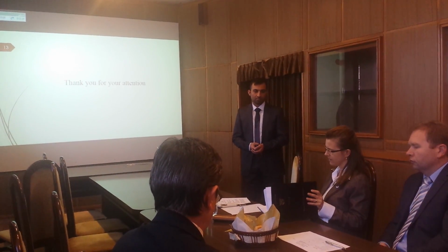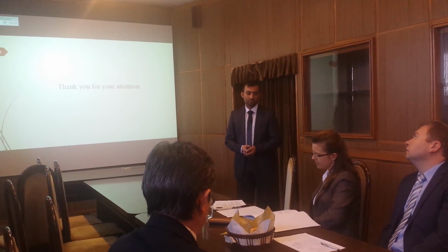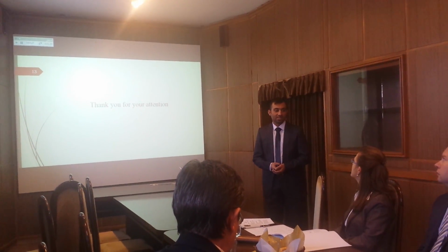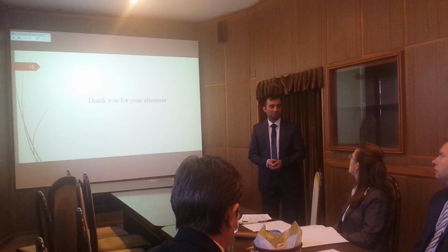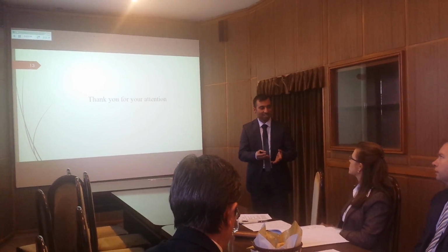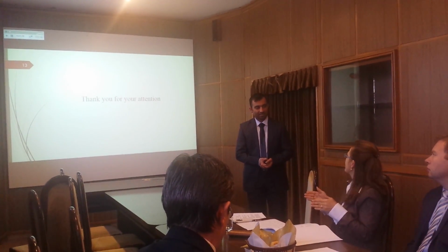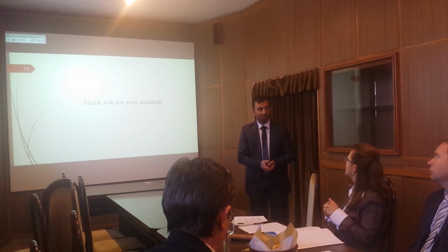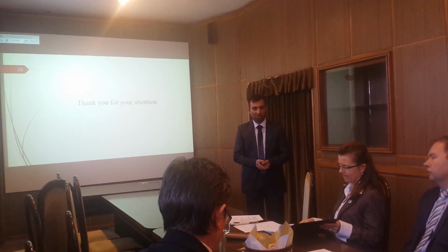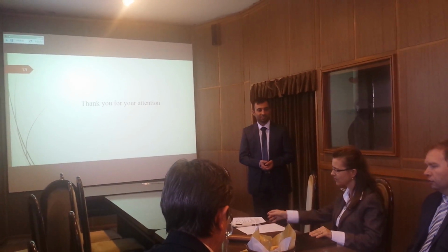One more question. You say that the indoor design condition, you say the relative humidity, and you put like 30, 40. I tried to find one, and which one do you use for this calculation? It is from the ASHRAE standard. Yeah, but for calculation you have to have one number, so which one do you use? 35. I see. It is a medium point between the two. Okay, I have no more questions.